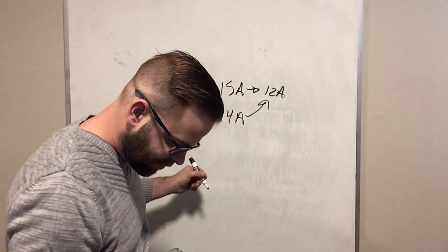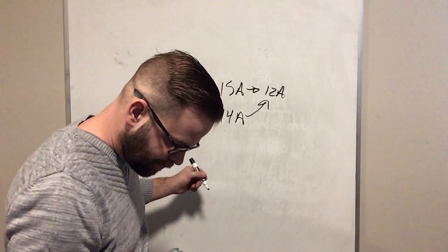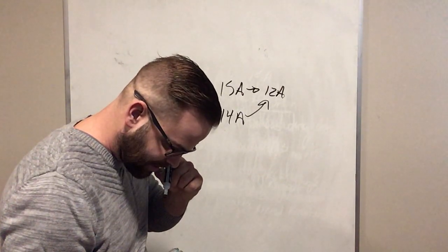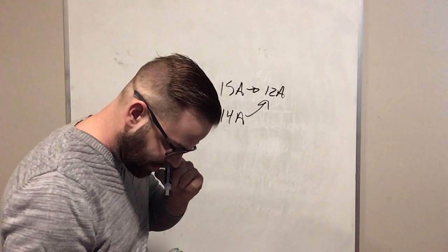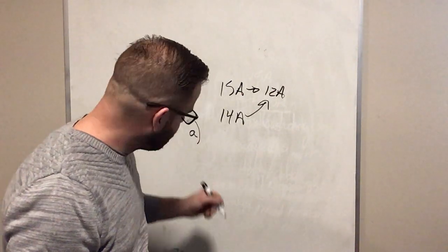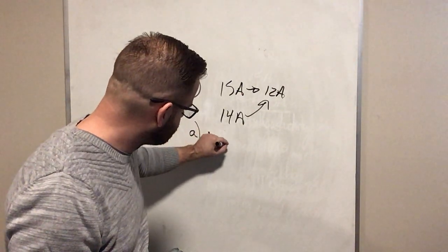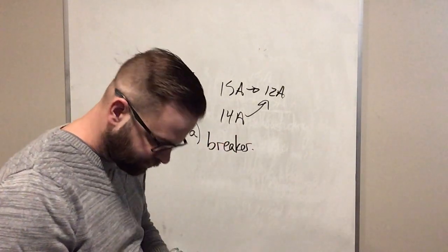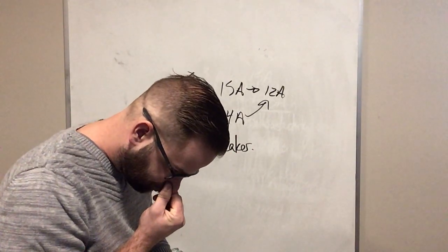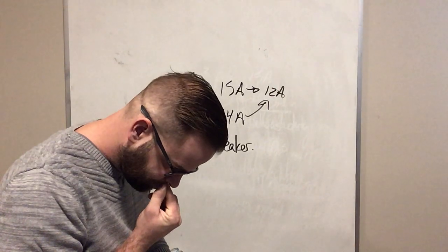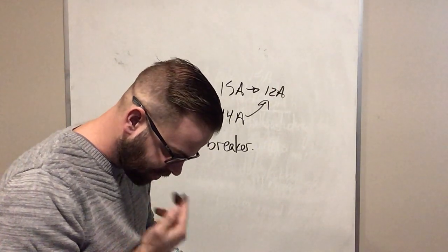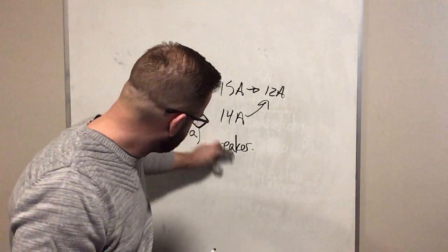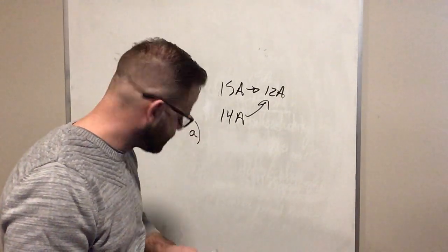I had a brain fart for a second. And except as that shall not exceed 80% of the allowable ampacity of conductors. Yeah, so my breaker, the continuous load, I was right the first time.